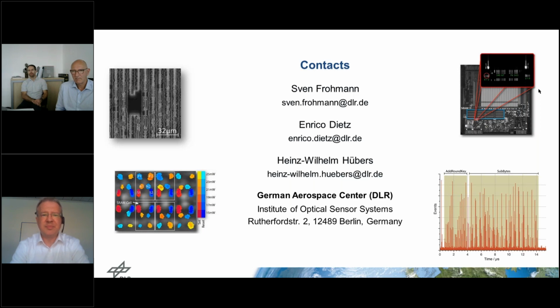It's not only that. When it shifts, it also means that the voltage of an integrated circuit was reduced further. And that means the number of electrons flowing through such a transistor is reduced. So you shift the wavelength to the infrared and you reduce the intensity. So there's a point where you can't measure it anymore. This is some critical point, the limit of photon emission.